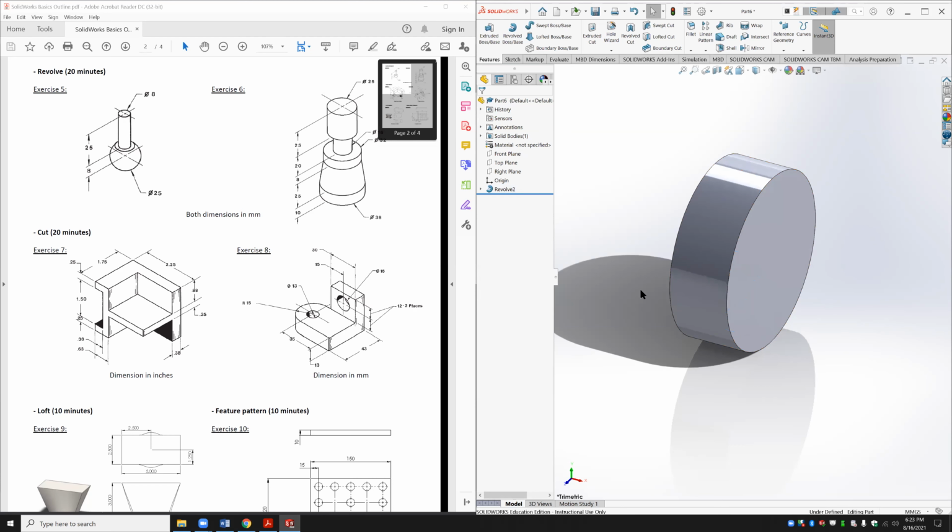You're welcome. So anyways, this is just a demo. Does it make sense how to use revolve? Usually you'll use revolve when you have circular symmetry with the part or the body that you're trying to create. And usually you'll use extrude when you want to create a 3-dimensional body with a continuous cross section somewhere in it.